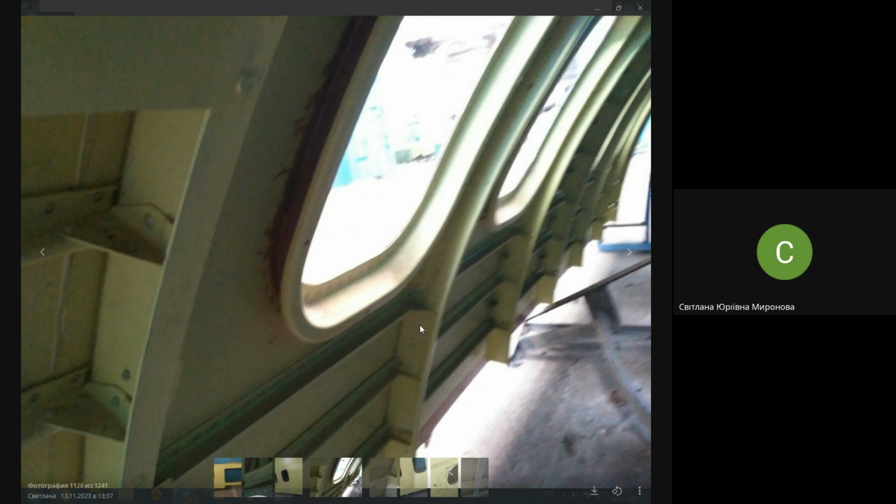And one more important element: wherever you have an intersection, they are not really cross-sected, not really joined. No, that is a special case because it's the end of a stringer in this place. Wherever you have an intersection, you have cutouts in frames. The stringer passes through this cutout, but frame and stringer are not really contacting.